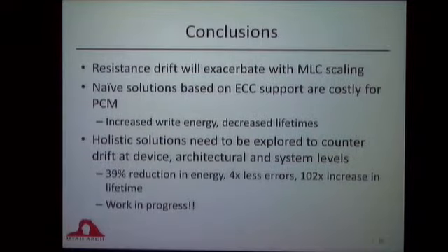So to summarize, what we believe is that resistance drift is a big problem in the current MLCs, and it's going to exacerbate as MLCs scale to have more and more states. Naive solutions based on ECC support are going to be extremely costly with increased write energies and decreased lifetimes. So what we need to explore are holistic solutions as we proposed in this paper.